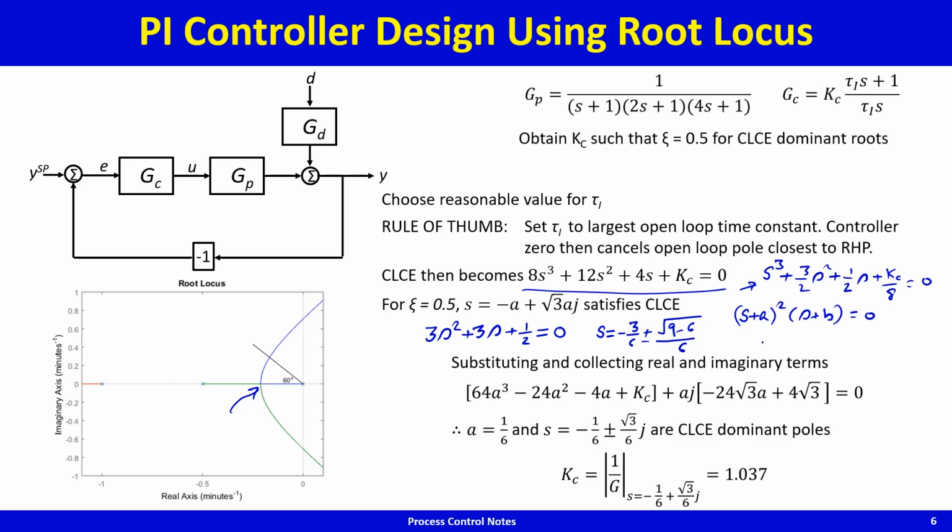So we'll get s equal to minus half plus or minus square root 3 by 6, whatever that turns out to be, you can calculate. This guy will be rejected because we want a root that is in this range. So we want minus half plus square root 3 by 6. How much is that? Whatever that is. So that's the breakpoint. So this is another way of calculating the breakpoint. But this technique will only work if the power of the characteristic equation is 3. If the power becomes 4, then you get a cubic.